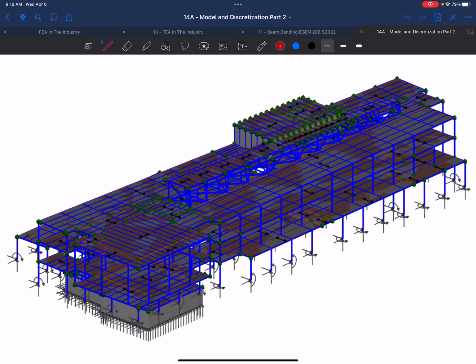Right, you have all of these joists where you're just taking 4 units and copying them over, same layout 4 or 5 times, and then they stack it all on top of each other. And so in that case, yeah, you break it up into hand calcs and just do it one at a time. Or you break up components and do it in another analysis software like Intercalc or something like that. Do you guys have Intercalc? Yeah. I remember Morley telling me any old schmuck could do the gravity design for a building, but he's like, we get paid to do the lateral design.